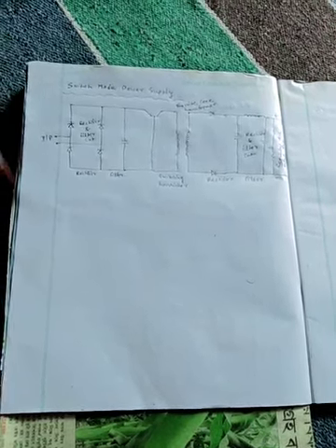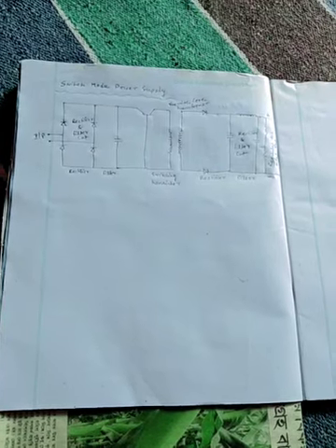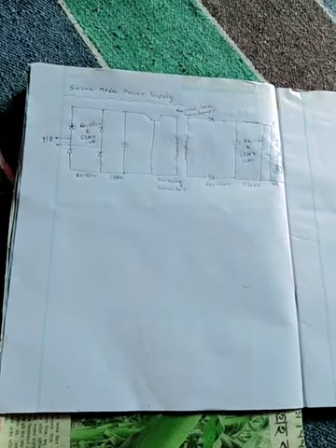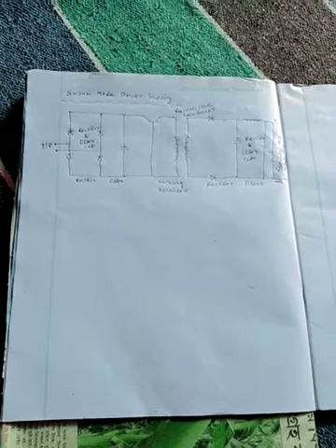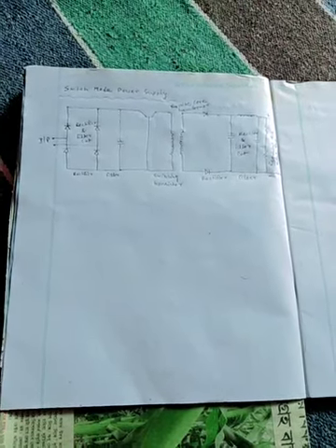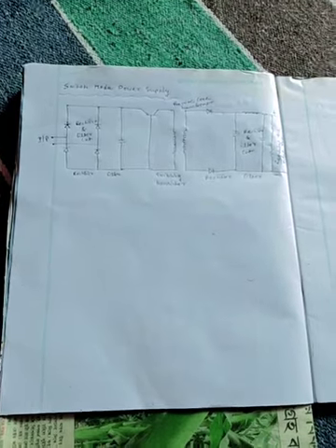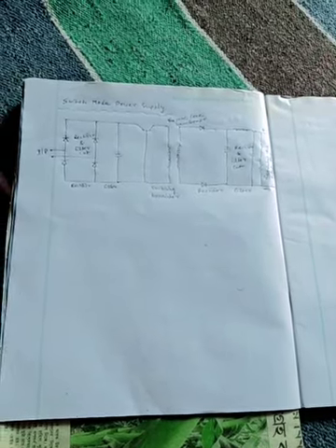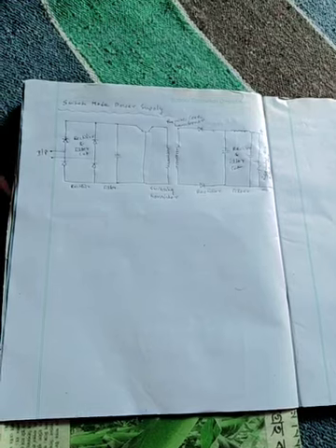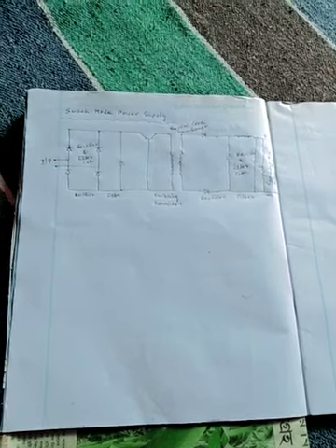The direct voltage is not stable and changes due to changes in the line voltage and changes in load current. So SMPS is a switching device and it is also a regulator. Regulation means making the output DC voltage constant in spite of changes in line voltage and load current.